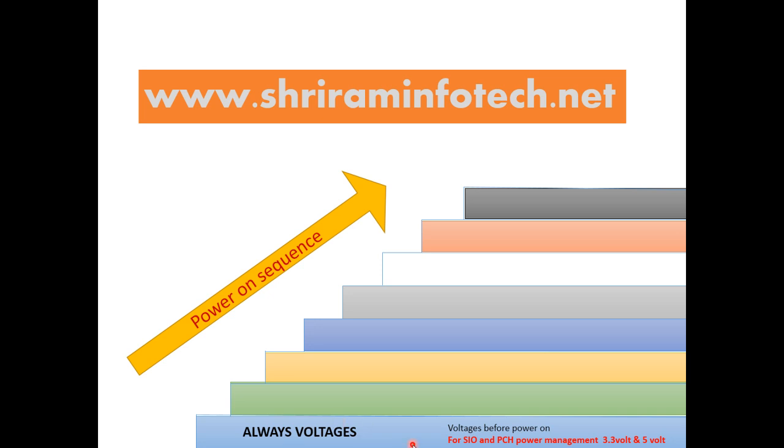And when you turn on the switch, all the other voltages come out: 1.5, 1.35, 1.05, 3.35, graphics and CPU core, and they go through the particular switches to the entire motherboard. So these are the power rails. The voltage that comes before power on is called the always voltage, and the other voltages come after the power on.